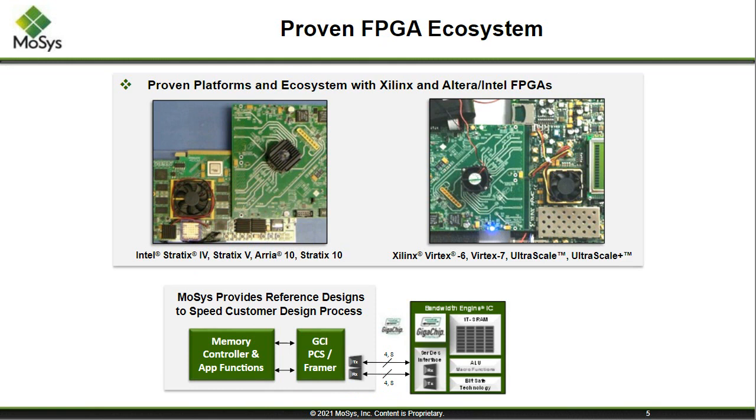So again, one of the things we wanted to do was, they always say, eat your own food. We wanted to actually say, okay, if we think SerDes work on a structure, maybe we should build our own boards and see how hard it is to do that. So we've built a series of these boards now, maybe 10 or so boards that have that FMC, the FPGA mezzanine connector, I/O structures. And we've built them to interface to all the Intel and the Xilinx characterization cards and things that they put out in the market. So again, we have actually done this work. We wanted to make sure that it's a viable product when you do something like this to talk to a memory.